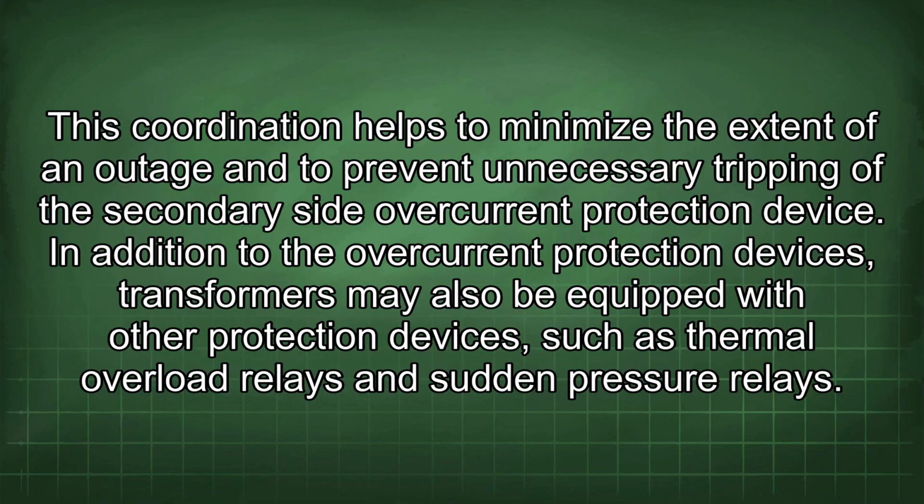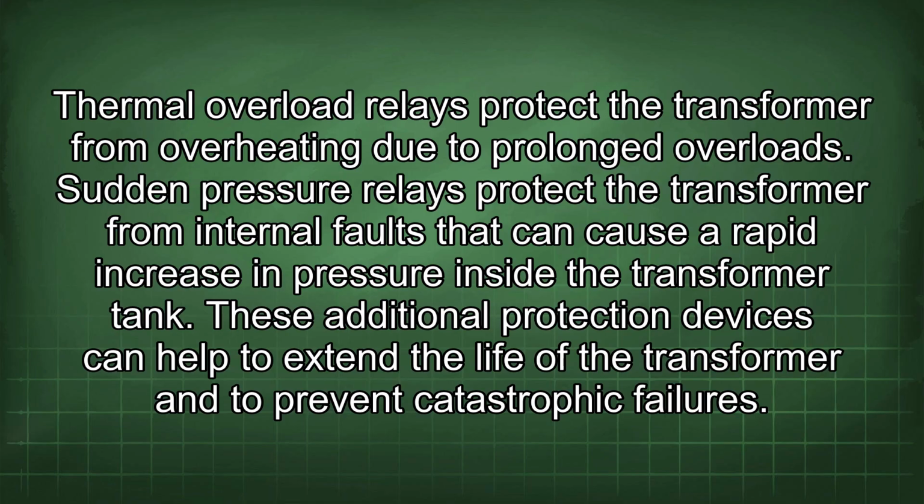such as thermal overload relays and sudden pressure relays. Thermal overload relays protect the transformer from overheating due to prolonged overloads. Sudden pressure relays protect the transformer from internal faults that can cause a rapid increase in pressure inside the transformer tank. These additional protection devices can help to extend the life of the transformer and to prevent catastrophic failures.